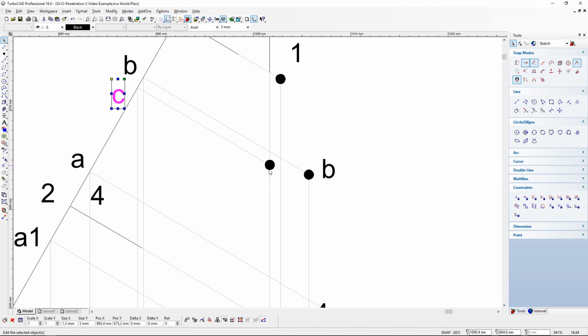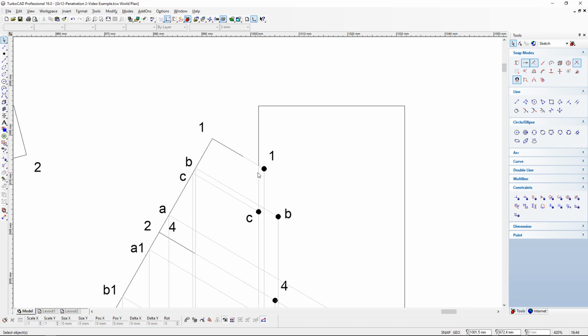And then I will also label this point here C, because that's the actual intersection that we want. So therefore we know that this edge of the cylinder from the top down to C, that will be the part where the cylinder now makes its bulge, and you will have everything behind that point as hidden detail.